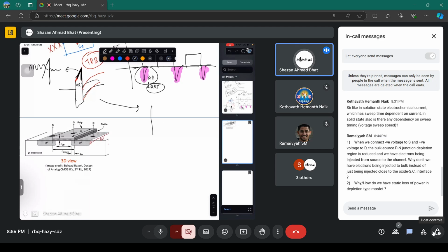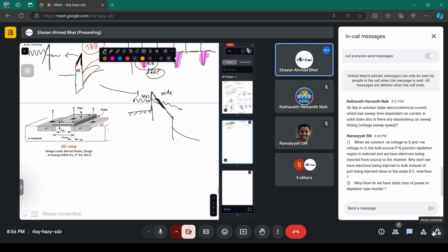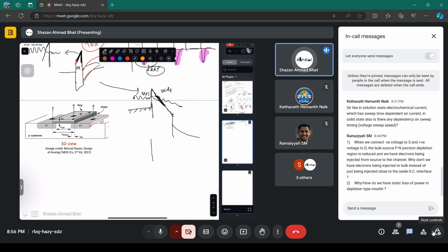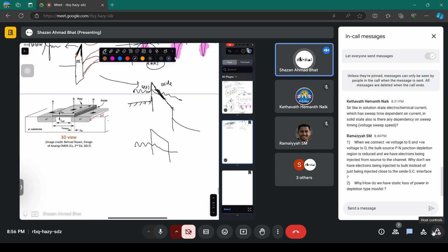If you have a tunneling barrier like this oxide, with a metallic layer on one side and a semiconducting region on the other side, the electron can tunnel through this triangular barrier, decaying exponentially, then appear on the other side. This is the wave function of the electron. In another scenario, if the electron tunnels in the triangular region, this is called Fowler-Nordheim tunneling, and if it tunnels through the full barrier instead, this is called direct tunneling.